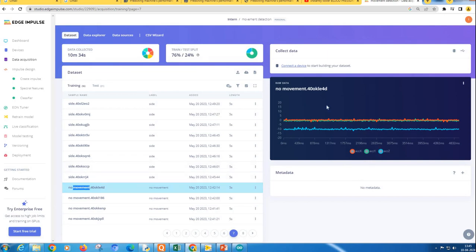The signals, all these three signals from the XYZ accelerometers, are sampled at a 10 millisecond interval, and a total of 5 seconds of data is created. So out of the 5 second data set, each 10 milliseconds, that means 100 samples per second, 500 samples will be there from each sensor, which goes as a time series data set into the neural engine.